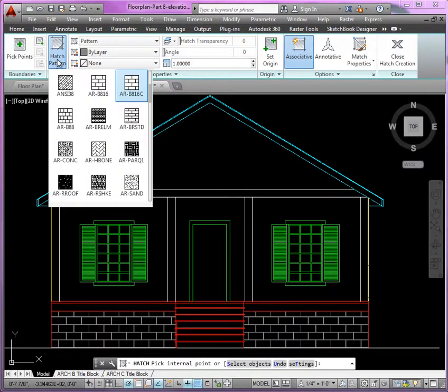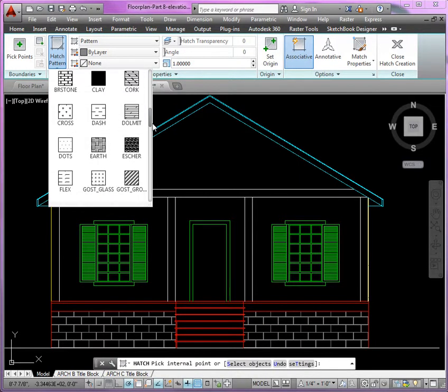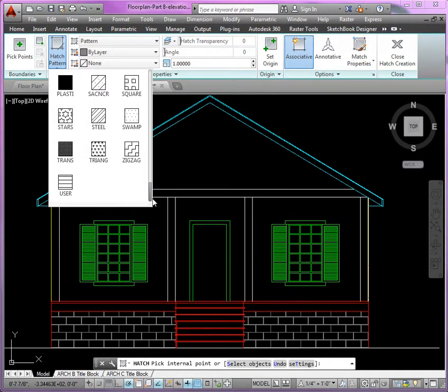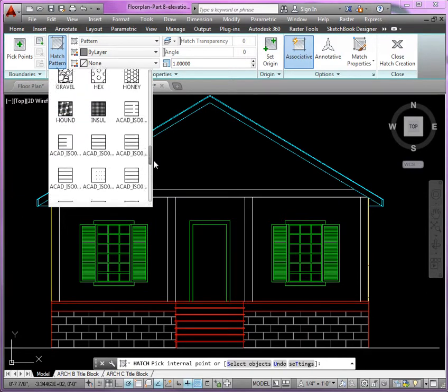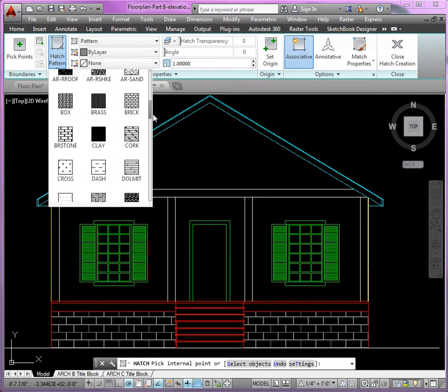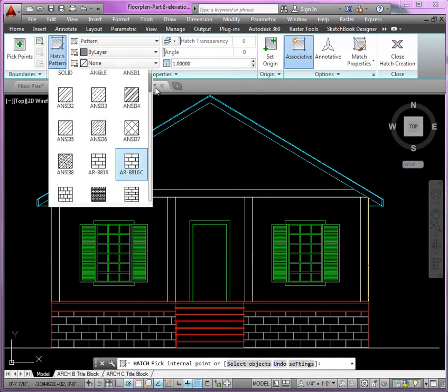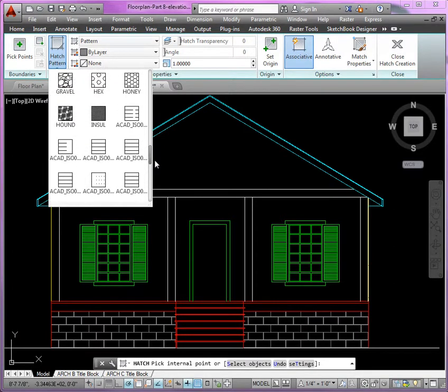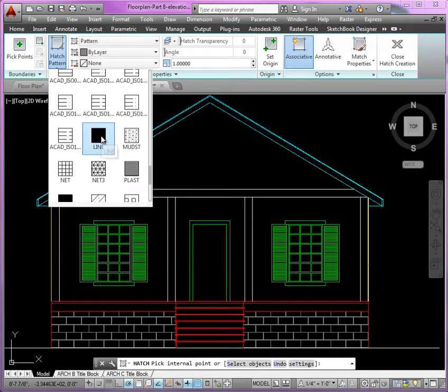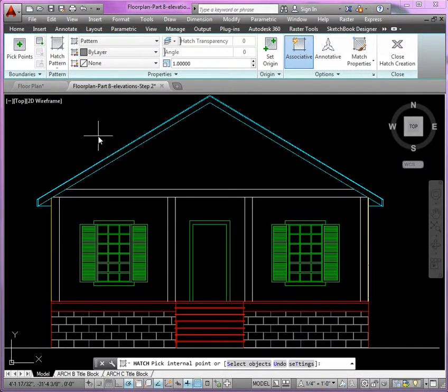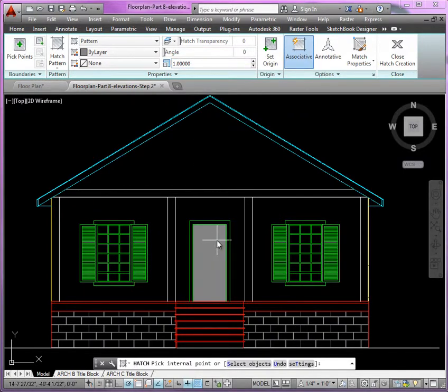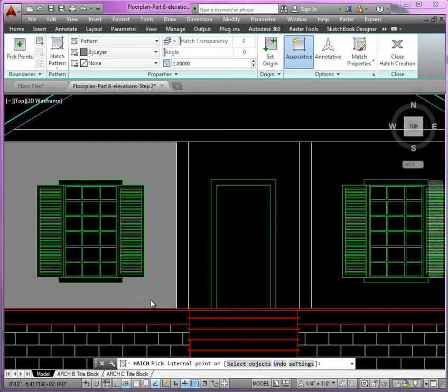If I go over here to hatch pattern, what I want to do is look at line. And I want to set up line in such a way that I get about 6 inches. Now you could be very technical here and do your measuring and some calculations to do it correctly, but where's line? Oh, there it is. There's line. If I use line, this just produces lines, and you'll notice I've got angle and I've got pattern scale.